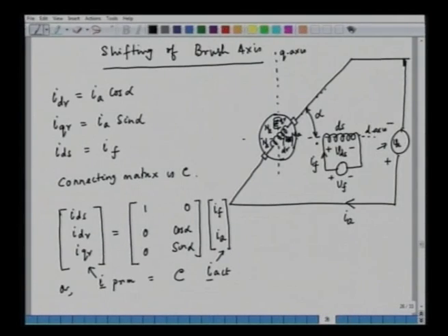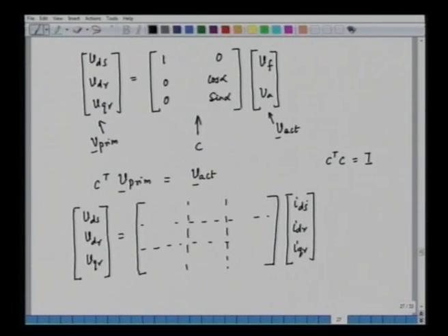You can see here that we have 3 windings, that is DS, DR and QR, and correspondingly we have VDS, VDR and VQR, IDS, IDR and IQR. So, that is what we have written here, and this would be the resistive drop plus LDSP. We can fill up this matrix by inspection. We do not have to remember this. The stator does not have any rotationally induced EMF.